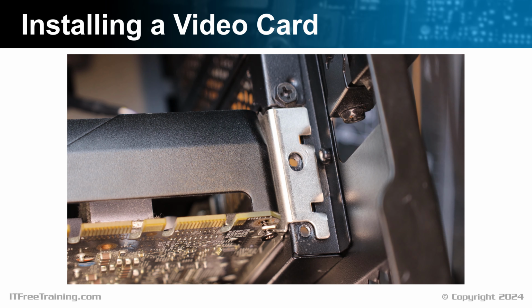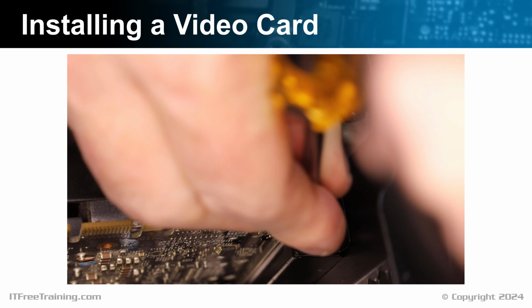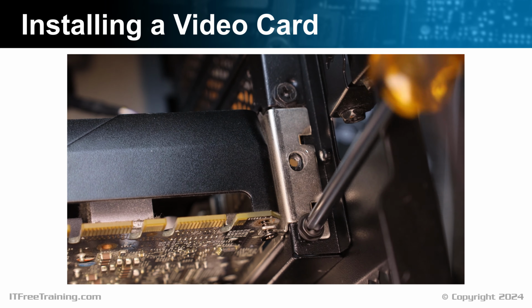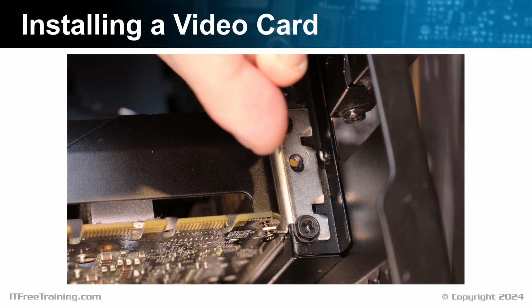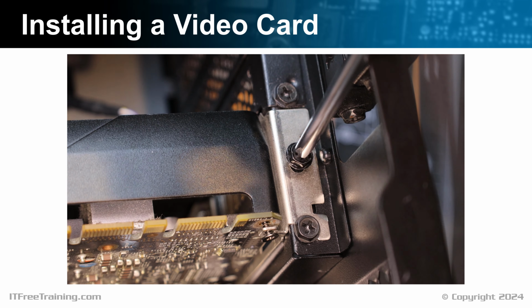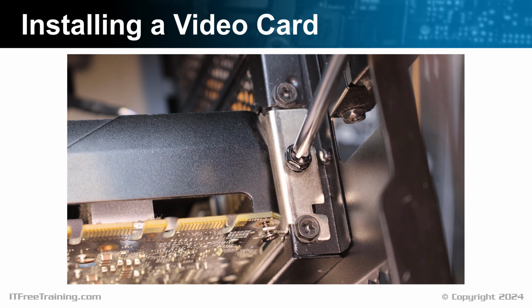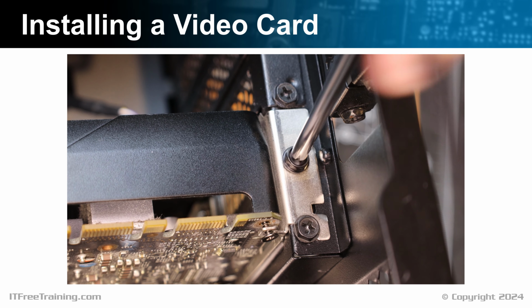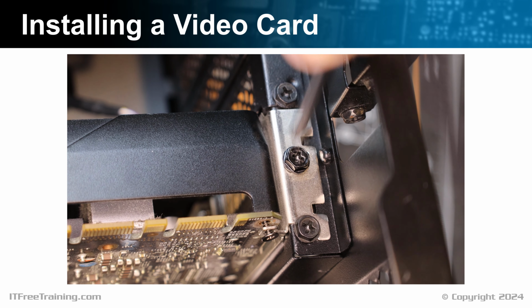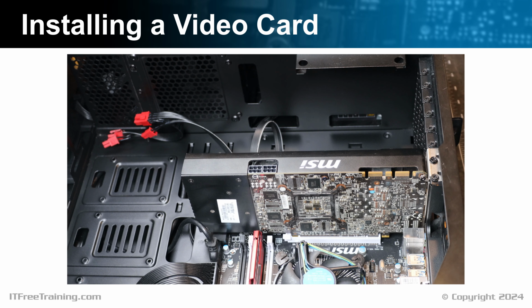The next step is to screw in the 2 retaining screws. This will hold the video card in place. It is important to put in these retaining screws because bumping the computer case or simply plugging in the video card can force the card out of the slot. If this happens, your computer will most likely restart and you risk damaging the video card and/or the motherboard.